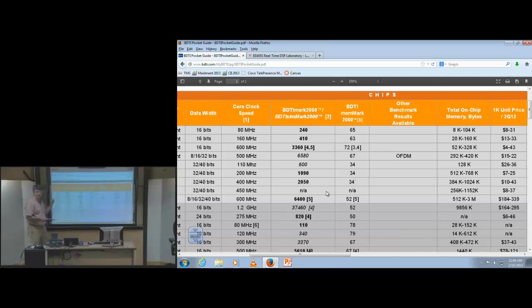Higher is better. These are about a dozen basic kernels written in assembly: FIR filtering, IIR filtering, a truth table, a convolution, complex FIR. It's just basic number crunching. It doesn't test the memory subsystem, the compiler, or the operating system. There's a separate benchmark for memory.